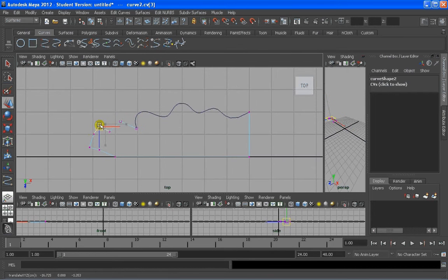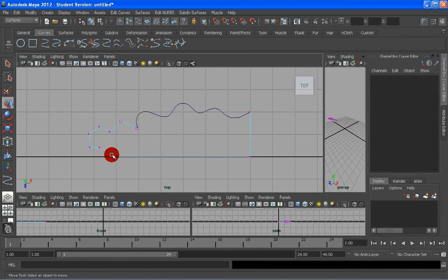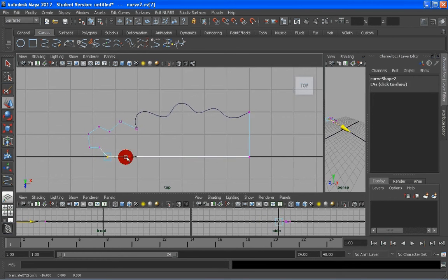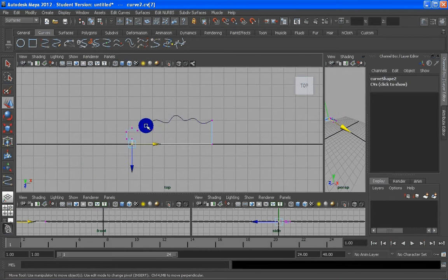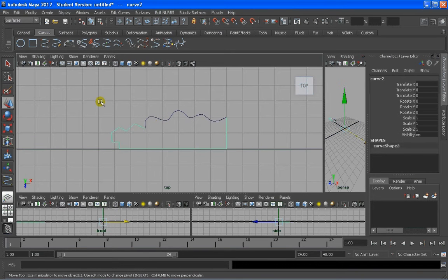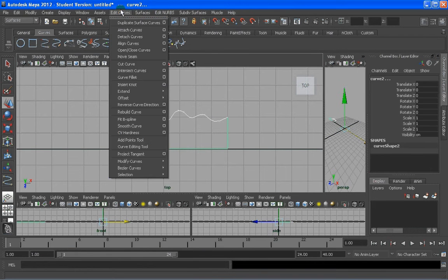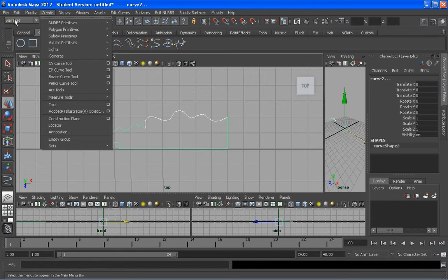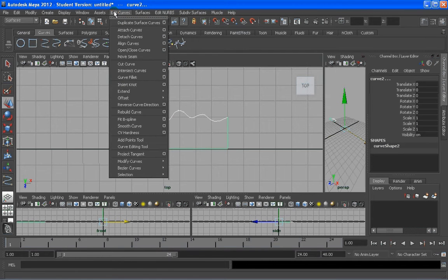This one could be here, and this one could be outside, and it could be even straight if you know, pressing shift, and you can create the straight lines in many ways. So the next step is for this section. This could be this section or whatever section you may have for your revolve. We have two curves, 1 and 2. What we want to do is select them both and say edit curves. We have to be in surface, of course, and edit curves and attach.